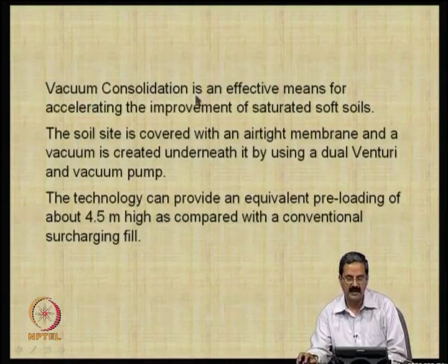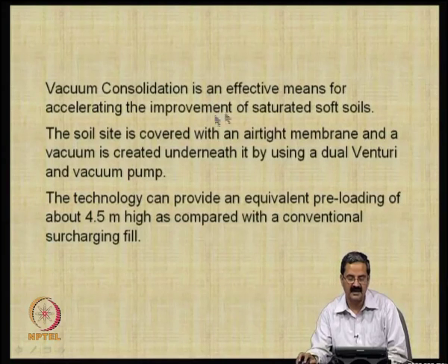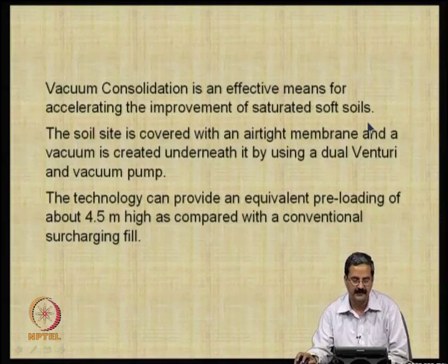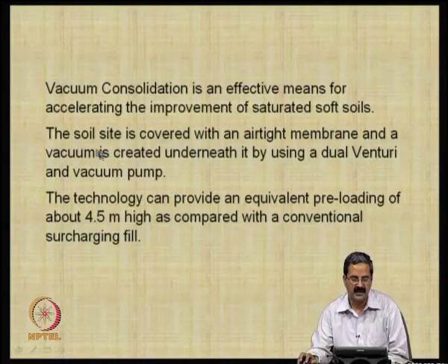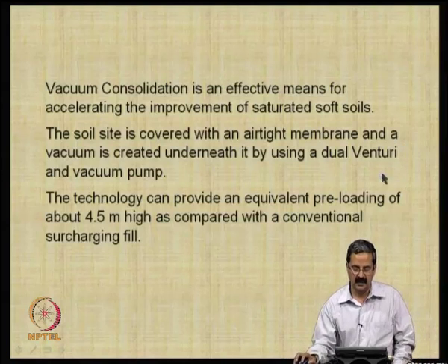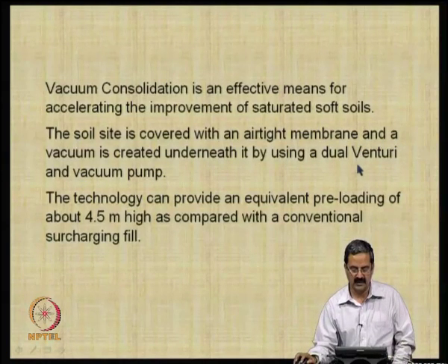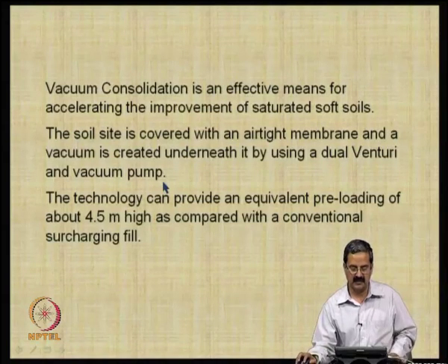It is an effective means of consolidating or accelerating the improvement of saturated soft soils. The soil site has to be completely covered with an airtight membrane, and a vacuum is created underneath it by using a dual Venturi vacuum pump. There is a pumping system here.